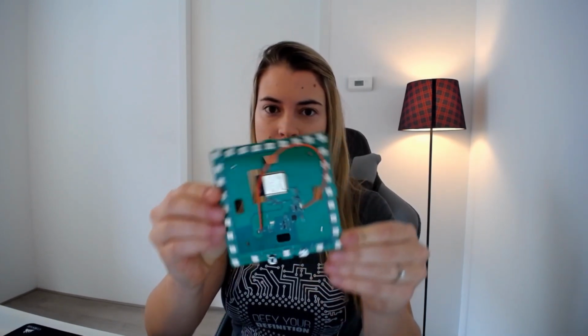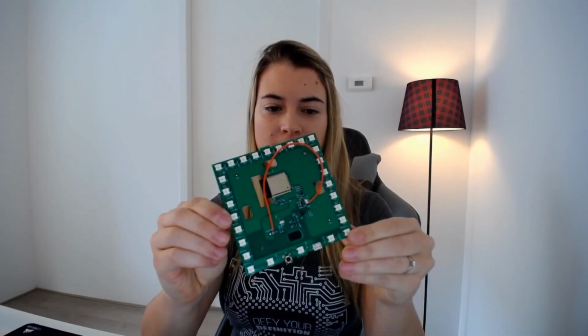So let me first give you some background about a PCB drawing. You'll see that the PCB drawing consists of multiple different layers, each with a different name for a specific purpose. For instance, if you look at this PCB, you'll see it's got quite a lot on it on the front and quite a lot on it on the back. And the manufacturer of the PCB needs to know how to manufacture it, and the different layers in our drawing actually communicate to them what holes they need to drill, what overlays they need to put on, what needs to be on the top, what needs to be on the bottom.